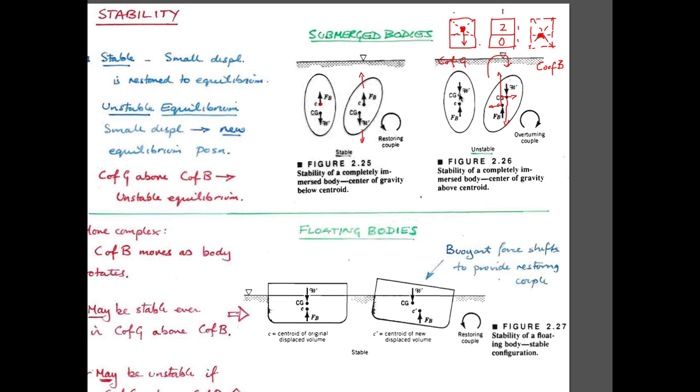But it's conditionally stable because if you give it a small motion to the left, someone moves around in the ship or it gets pushed by a wave, then the net couple that is applied by the moment between the center of gravity acting downwards and the center of buoyancy acting upwards rotates it until it finds its new stable position, and the new stable position would be this geometry here where one is below the other. And so you can imagine that that's basically what's going on.